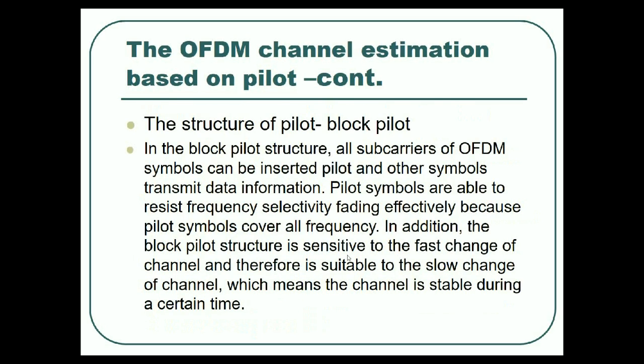Here I want to talk about the structure of the pilot. The first one is the block pilot. In the block pilot structure, all the subcarriers of OFDM symbols can be inserted with pilots, and other symbols transmit data information.